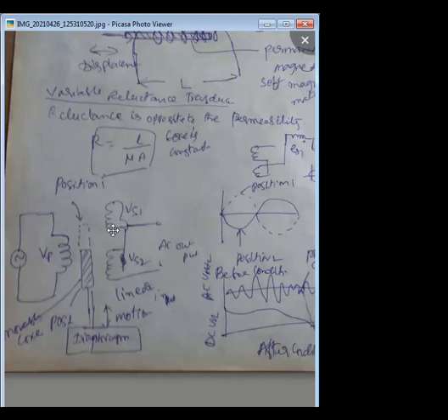From secondary winding 1 we will get the voltage E1, and from secondary winding 2 we will get the voltage E2, and by series opposing connection we will get the difference of these two voltages. Another type of connection is the series aided connection, in which we connect them in series nature, and by that we get the addition of the two voltages.